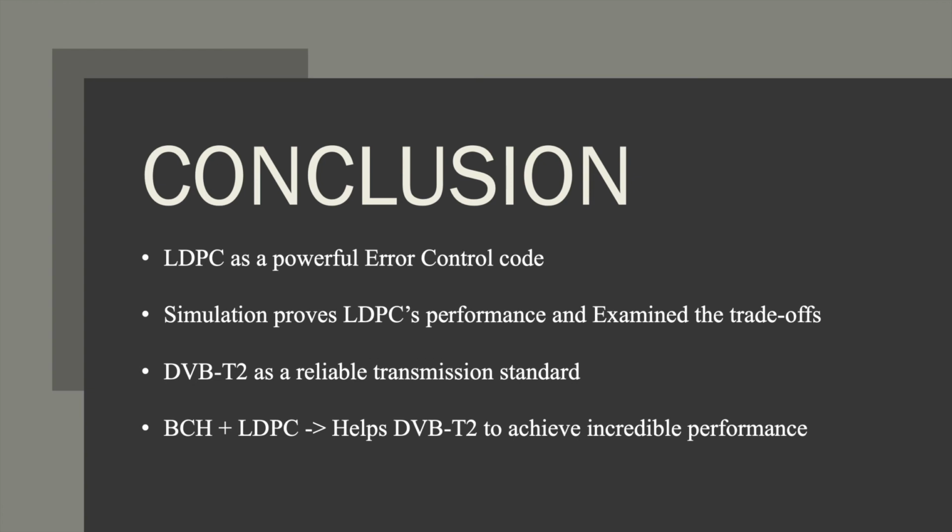The more iterations processed, the more accurate the code is. With the same BER, for more iterations, less SNR would be required. By observing the results, it proves that with the help of BCH as outer coding and LDPC as inner coding, DVB-T2 is a reliable system in the digital video broadcasting area.